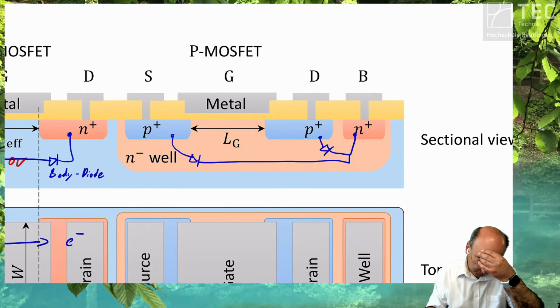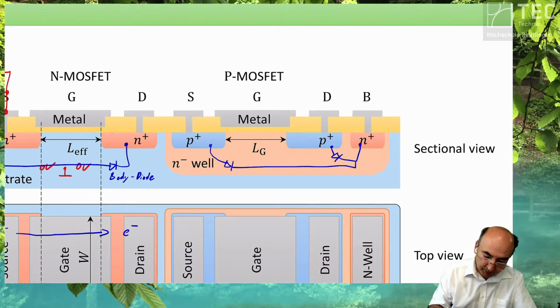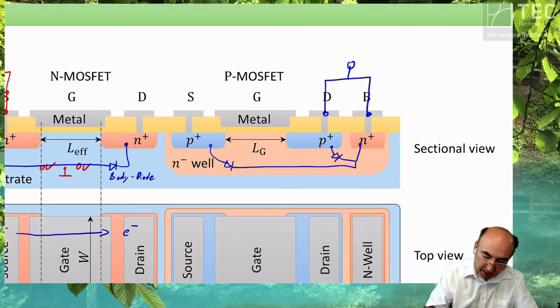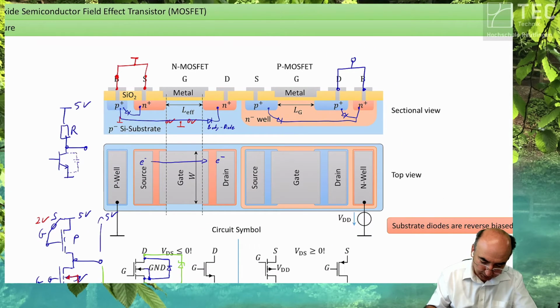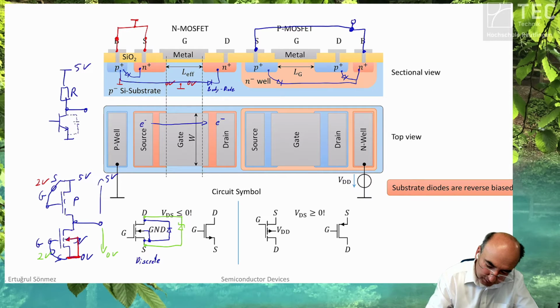So now, if you put the drain above, no, below, one moment, the drain is all the time at the negative side. One second. Do we have an error? Drain is up. No, it's okay. So the source is up and the drain is down. This is the error I have made. You have to wire the source and the bulk together. This was my error in my drawing.